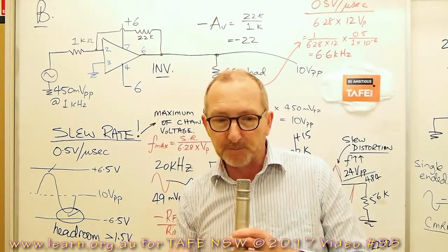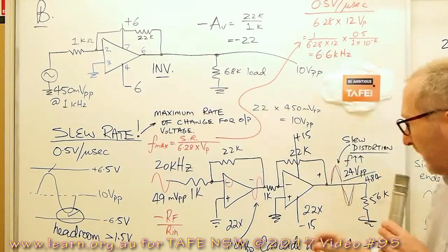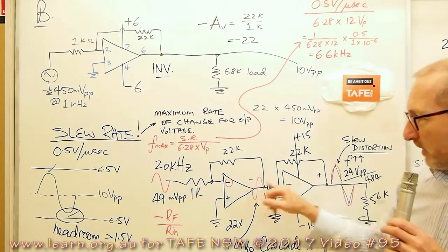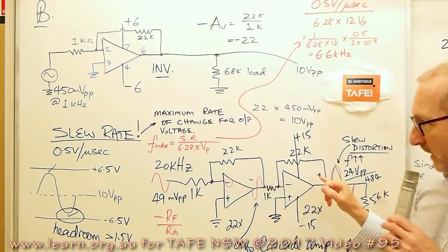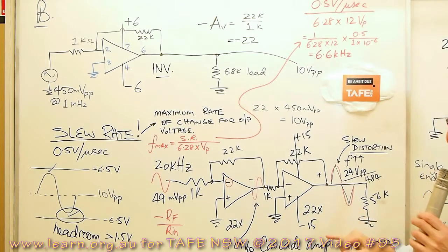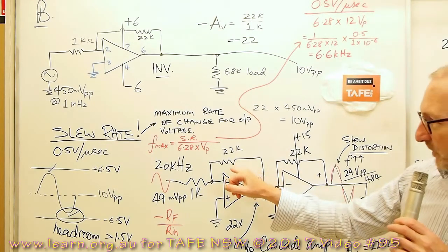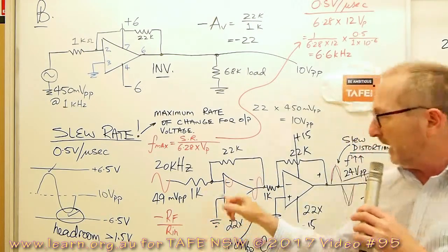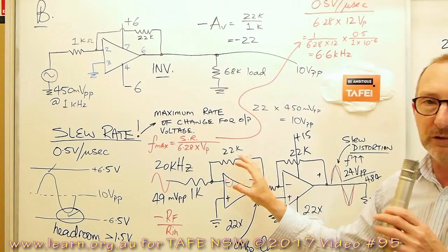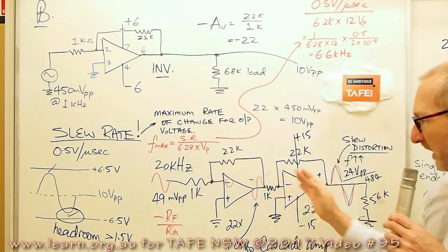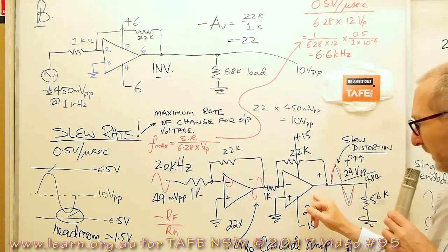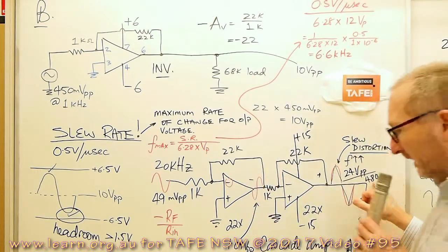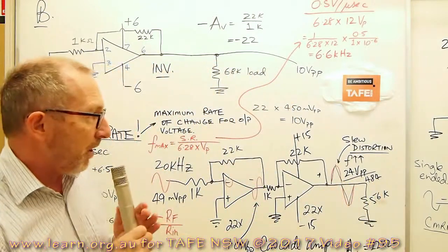Well, one of the labs which we've done today had two operational amplifiers in a cascade configuration. We set the resistors, the RF and RIN, to 22K and 1K respectively. That gave us a gain of 22 times in each stage. With cascaded amplifiers, 22 times, we've got to multiply those together to get the overall gain. I've done that and I got a gain of 484 times.